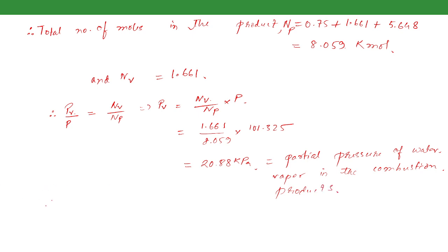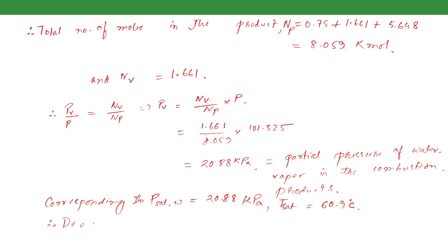And corresponding to the saturation pressure of 20.88 kPa, the saturation temperature is 60.9 degrees Celsius. Okay, therefore the dew point of the products of combustion is 60.9 degrees Celsius.